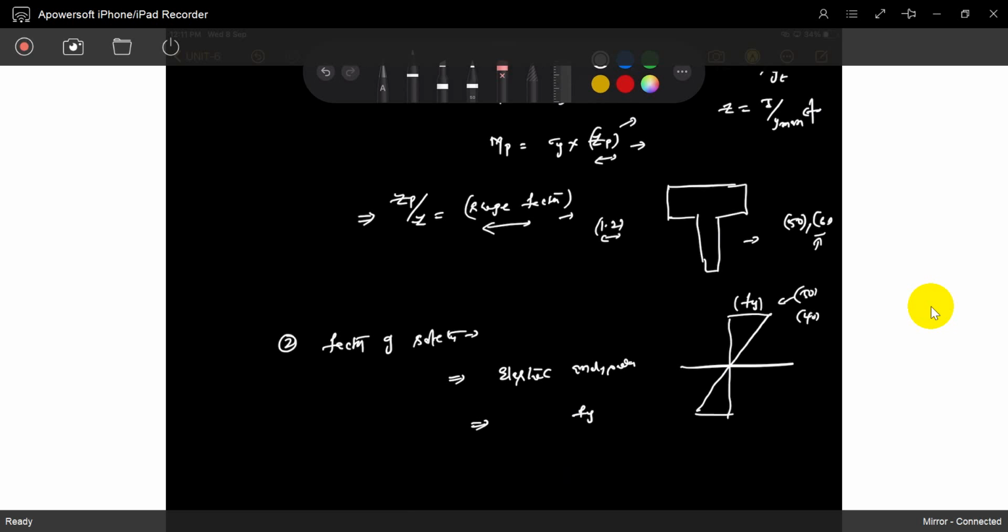We won't design the system reaching Fy. We will design the system so that it won't reach Fy; it's below Fy, because we won't stretch the system up to the edge. Understood? If Fy is 250, exactly 250, we won't design for that. We will design the system reaching only 200 or 150 or 160. We will maintain some factor of safety.